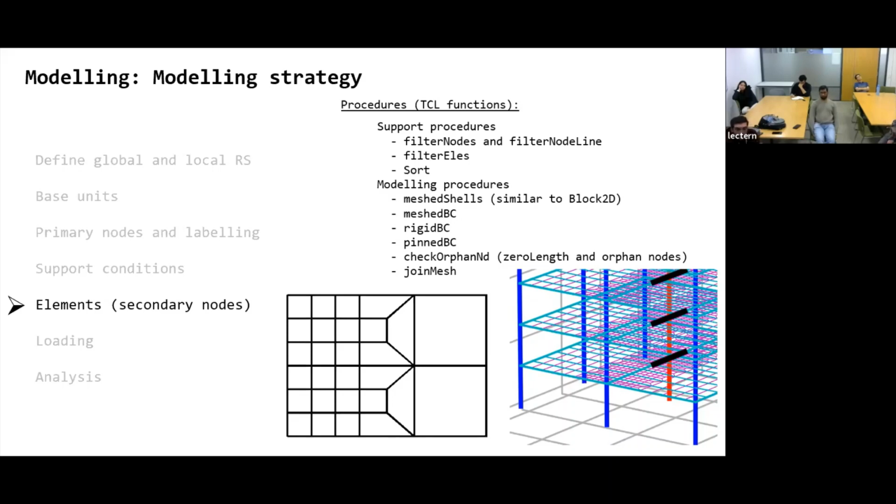I needed to create a way to join two different mesh sizes, because as I said, I cannot just connect that node to that node and then this node to this node if all these three nodes will be flying free. So the best way that I found was this discretization scheme, in which I can connect all the nodes, and there are three elements that are a little bit irregular, but they do the job.